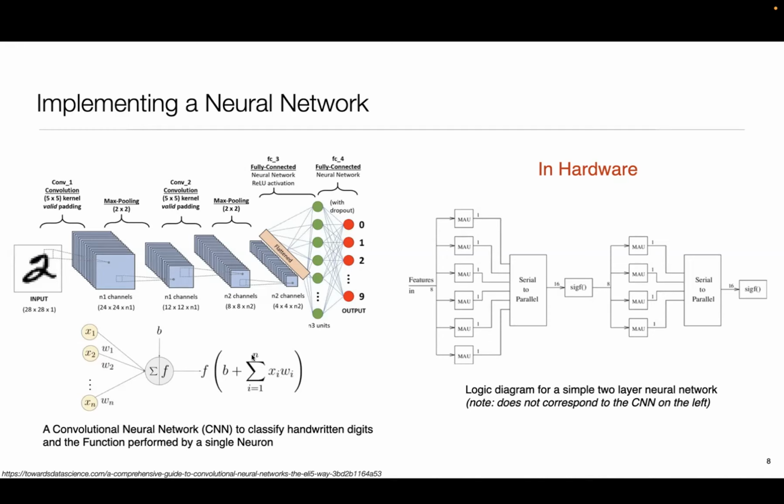But in many cases, the chip vendor itself may provide you some sort of a macro, some sort of a description of how a multiply accumulate unit can be created on the chip. So the chip itself may provide very low level primitives, but much like a software library where someone else writes the functions and you use the functions, same thing with hardware. There are hardware libraries, often called core libraries, which basically are little descriptions of how that thing is made using lower end stuff.